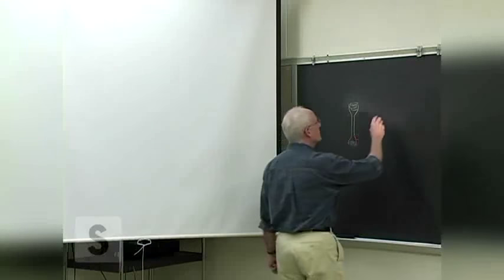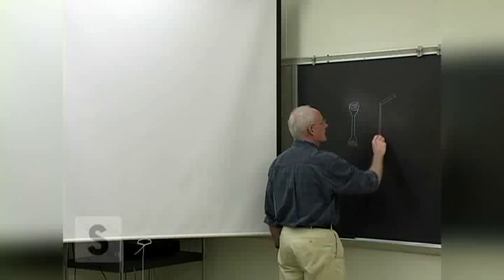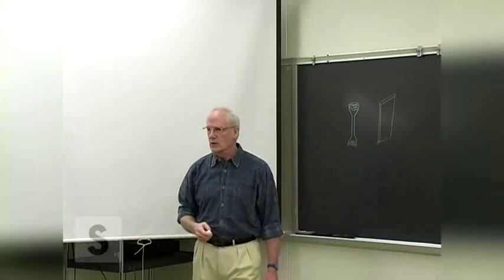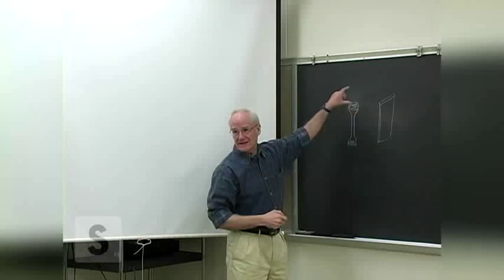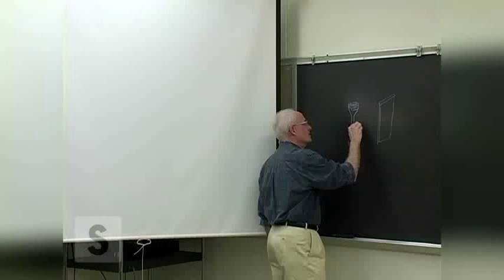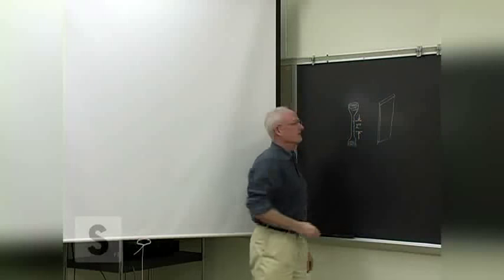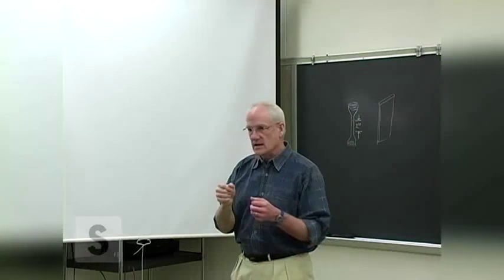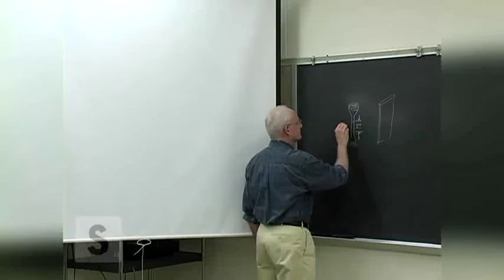There's also lots of examples of a sample that looks more like this being tested rather than this kind of thing. It does take a different machine, or at least different jaws in the machine. Typically about 2 inches on either side of two little marks that are put in, and then that is the starting length, what we call the L0 of the piece.